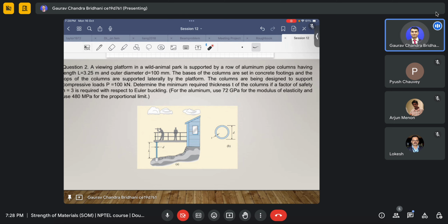For a rectangle there is a defined way, because in a proper rectangle you will find that Iyy is always lesser than Izz. So when that is there, you already know that it will buckle about Iyy because that is less. But for figures like a circular cross section or a square cross section, where you have the same I in all directions, it depends on other, external factors, like the eccentricity of the load.